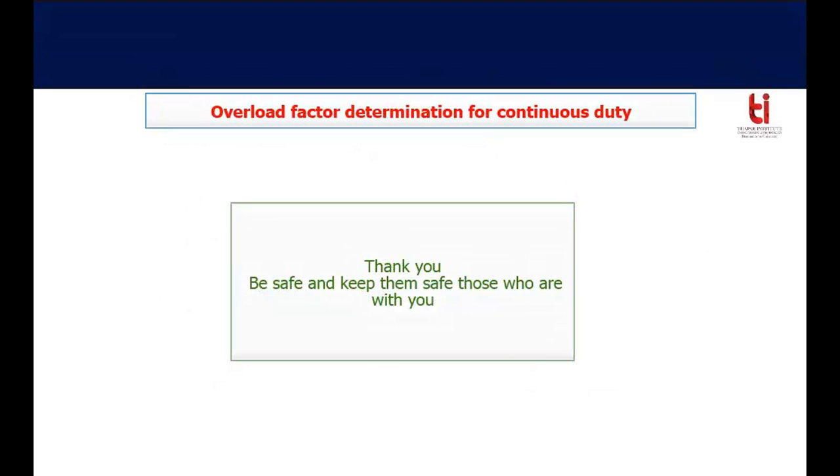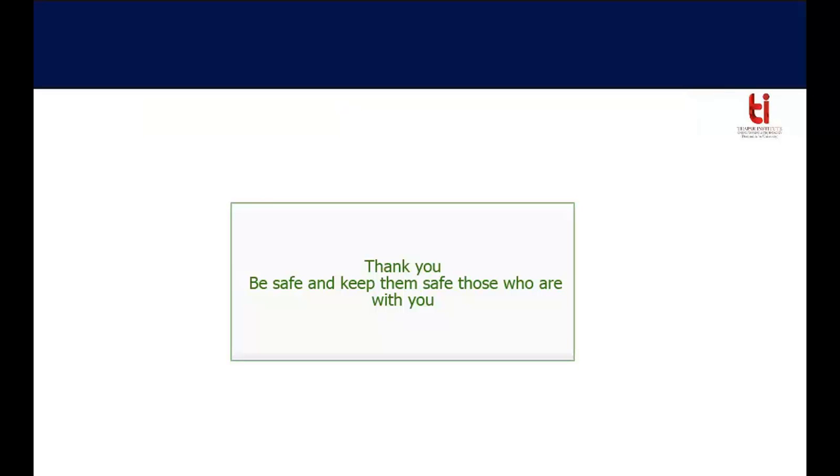Today we have discussed about how to find motor rating in case of continuous duty, in case of fluctuating and intermittent load. At the same time, we have discussed about if a machine is developed for continuous duty and if it is used for short time duty, then how much will be the loading factor.